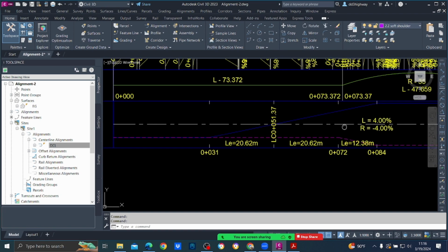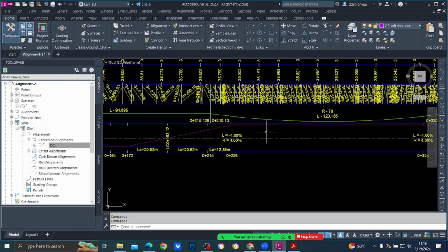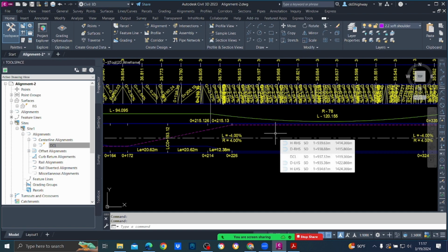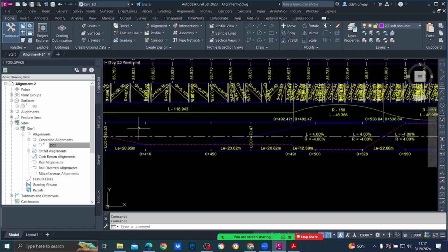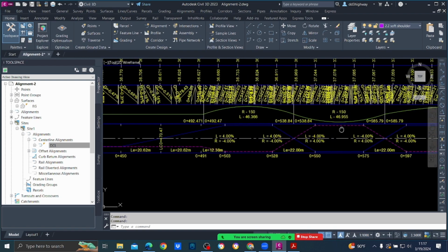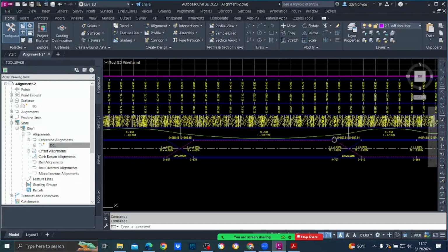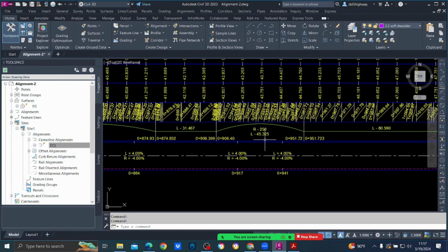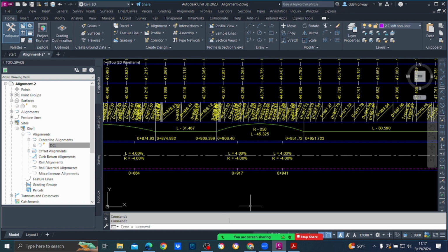Now this is okay if we are following whatever standards are being used, like say Roadway Standard 2018 or something. If you are going to use that, then this is okay. But unfortunately we are not using that. Therefore this super elevation development, if you are going to provide this, it's wrong in the Sri Lankan context. Maybe in American standards this is okay. Understood? Now please remove this again, right?